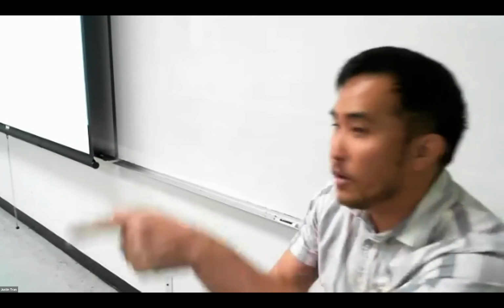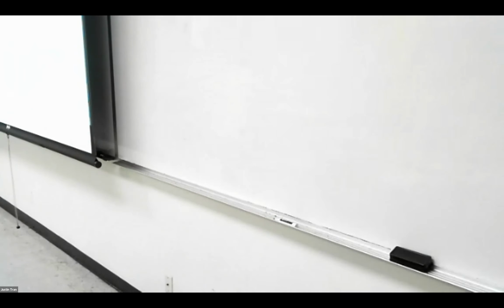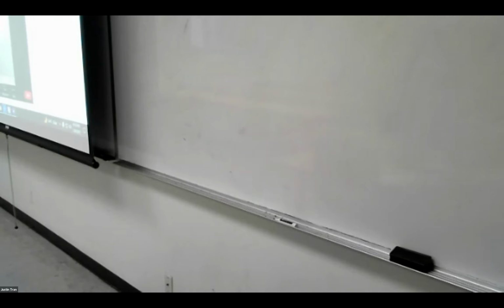All right. Anybody else having issues with this activity? Yep. Okay. Oh yeah, I tried to keep up. I didn't apply any sizing, so I just did a dummy mesh. So it was a pretty bad mesh. So you're going to want to do those things. There are more instructions. Oh, okay. But basically, you at least want to change the size. You want to make sure that all the elements are okay.